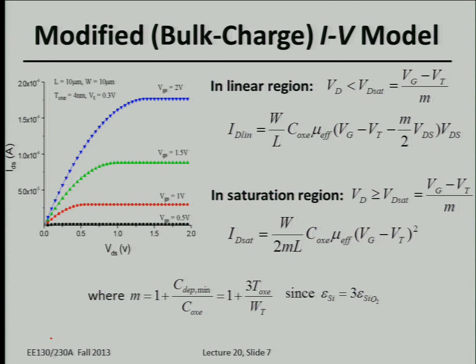After these corrections, the drive current in both regions of the MOSFET gets reduced. Previously, you overestimated the inversion charge by ignoring the spatial variation of the depletion charge. Now, after correcting for the VT distribution in the channel, you get a reduced drive current.